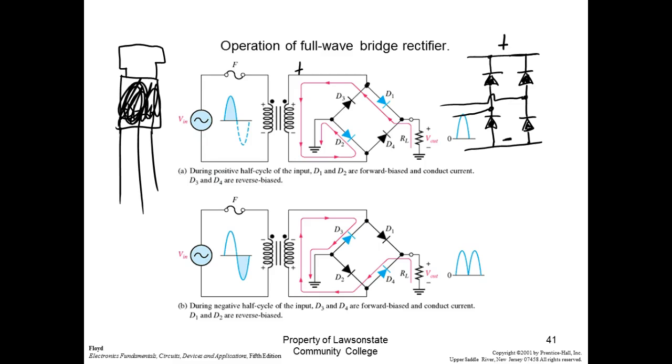But we can look inside one of these power supplies used by these desktop computers, and they'll have one of these devices in there. Normally, they'll put the diode symbols in. So we can get them common cathode, or we can get them common anode, depending on whether I'm trying to get a positive supply or negative.